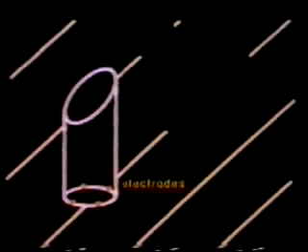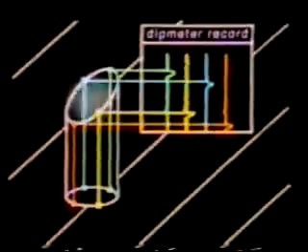The dip angle of inclined strata can be determined by a special variation of electric logging techniques, the dip meter. It's based on the simple principle of non-linear points, in this case, the logged records of 4 electrodes, defining a plane.